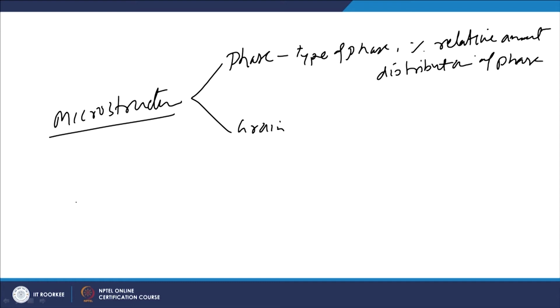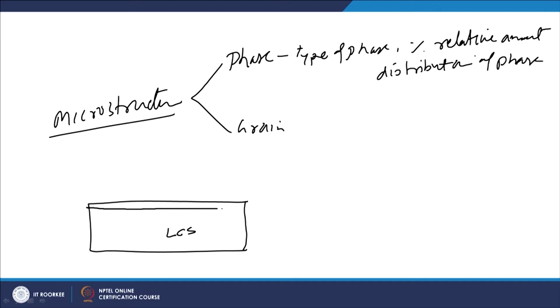For example, we start with the carburizing of the low carbon steel. We perform the carbon enrichment of the surface layers up to 0.8% carbon, followed by the hardening. The hardening is performed by heating the component to the austenitic state, followed by the rapid cooling for having the martensitic transformation.